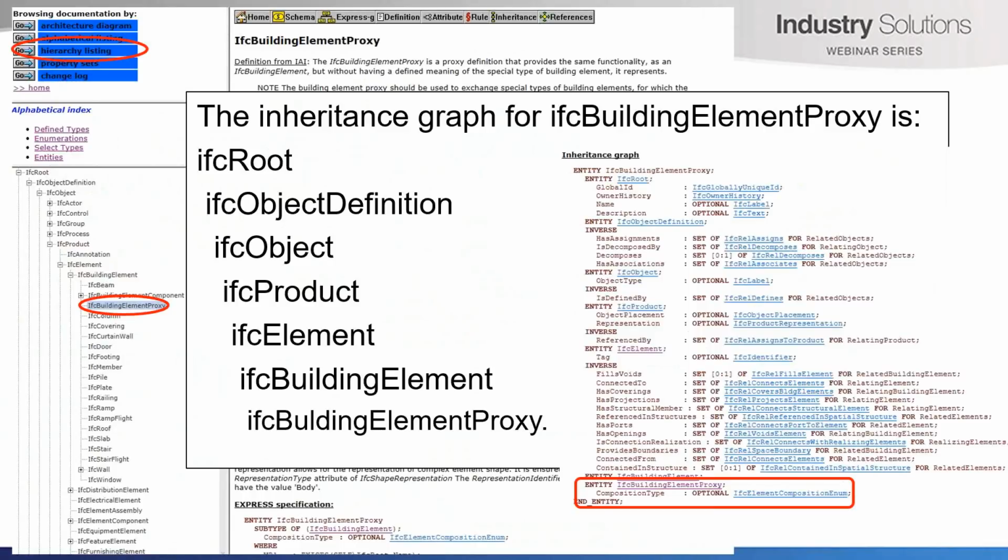So when you have an IFC element, it always has that information. Where it says it's optional, in files like what they call a STEP format, which I won't scare you by showing you one, where they have a $, it means that's an optional bit of information. So $ means we're not going to have anything in there, just so you have the correct number of fields. So basically, they're the sorts of information that every element has. In this case, I've done building proxy, whereas say a door might have some other information that potentially goes with it.